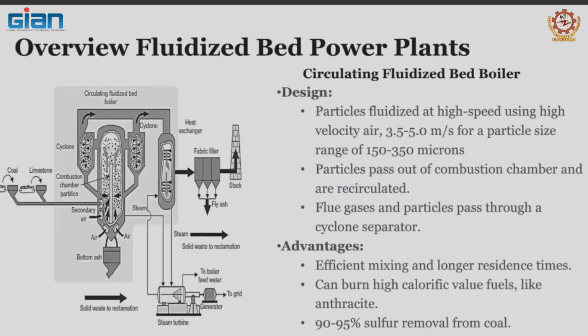So we had a look at this before. You have basically coal preparation here. After it is mined and brought to the site, it goes through a crusher, but a crusher is not the same as a pulverizer, it gives a much larger size, and it also eliminates some other non-coal particles. There could be some metals in there, and it goes through magnetic separators, and here you have coal being fed.